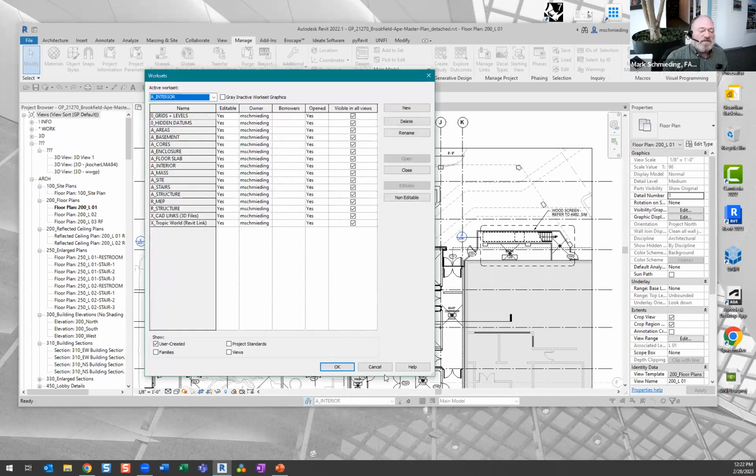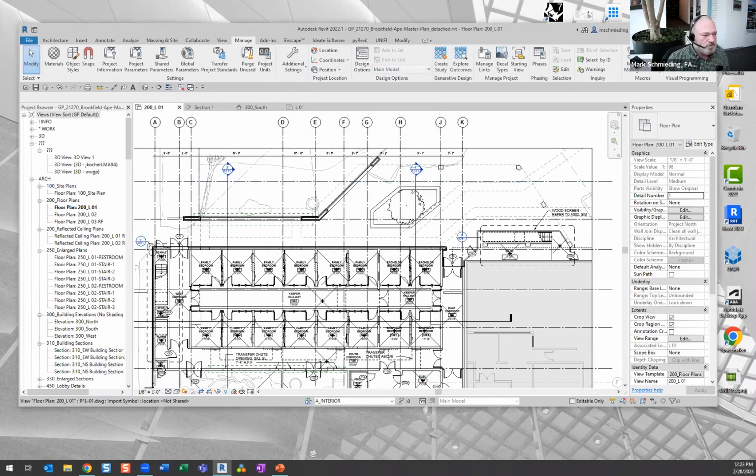Right. And the interesting thing is Revit, whether it's LT or regular, does not let you save a template file with work sets. So because these are important to us, what we do and what a lot of people do is just have a project that you've developed, and then save it as a project but delete all the stuff. And then instead of using the templates, we just open a blank project. It has everything we want. And that's usually where we start from. Okay.